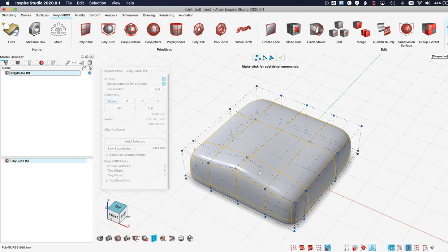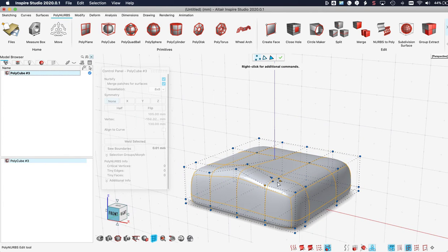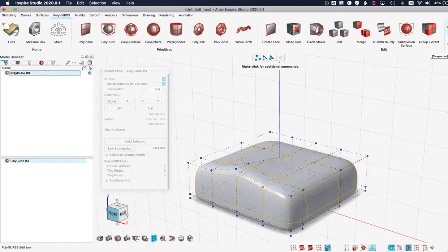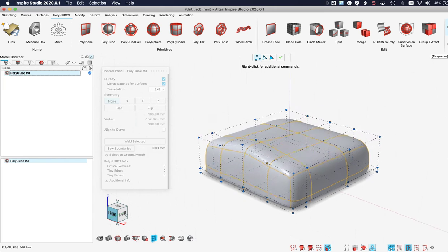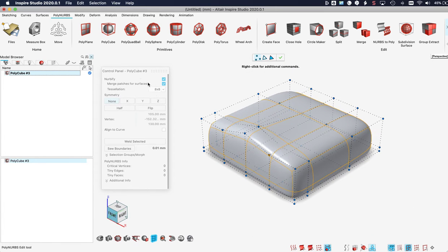So let's move them up a little bit, so I get this bump for the legs. Let's do the same for these two, but now what I would like to happen is everything I do on the right side also happens on the left side, otherwise I have to do it twice. So what I do, I introduce a symmetry. In the control panel, I click symmetry in the X direction, and immediately I get a red square indicating that it is a sort of a mirrored setup now.